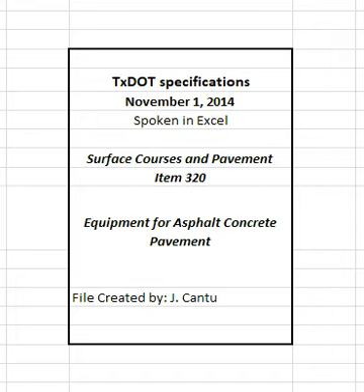2.1.1.1 Aggregate feed system. Provide a minimum of 1 cold aggregate bin for each stockpile of individual materials used to produce the mix. Bins designed to prevent overflow of material. Scalping screens or other approved methods to remove any oversized material, roots, or other objectionable materials. A feed system to ensure a uniform, continuous material flow in the desired proportion to the dryer. An integrated means for moisture compensation. Belt scales, weigh box, or other approved devices to measure the weight of the combined aggregate, and cold aggregate bin flow indicators that automatically signal interrupted material flow.